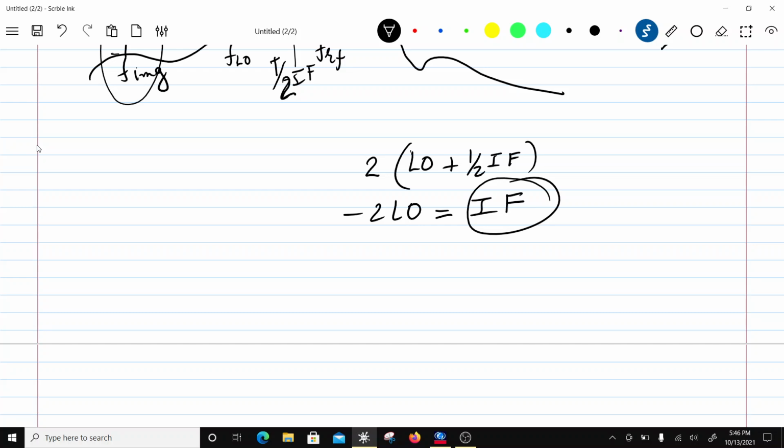While in case of direct conversion, the requirement on linearity becomes more stringent, because it's not only the even order mixings which are going to appear in the baseband, but also the odd order mixings will come into baseband, right?